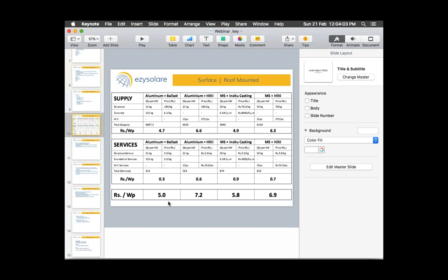One of the important things that we missed in our webinar is the fasteners. My personal question to Gurpreet and Satish, especially to you, is what kind of fasteners are you recommending? For mostly aluminum structures, SS fasteners are better. And for near coastal zones also SS fasteners. And now in the market, Dacromet fasteners are also playing a major role in corrosion resistance, and hot dip galvanized bolts for the normal zone locations.